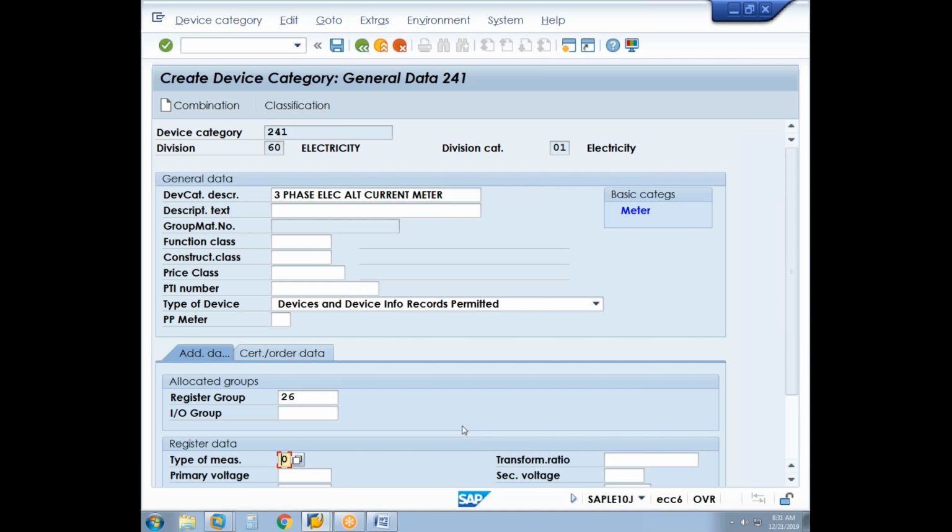So we'll have two devices, one a small transformer we are adding with the meter. The transformer is basically transforming the electricity to the required voltage and current. So the meter is reading the consumption according to the output of the transformer, which is coming as 20 amps, but actually the load current is 200 amps. So the meter is showing the consumption happening at 20 amps, but the actual consumption is happening at 200 amps. So there the system will calculate the billing ratio.